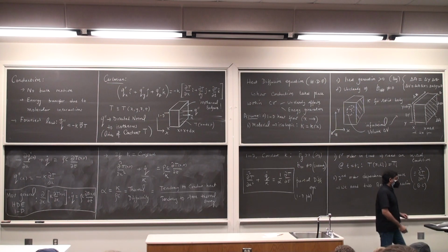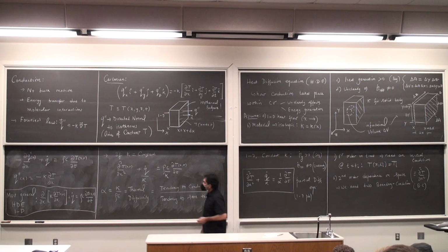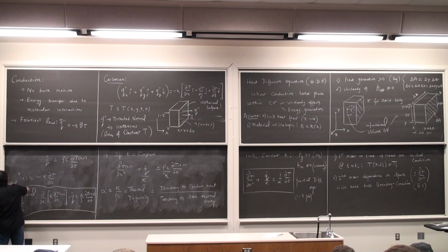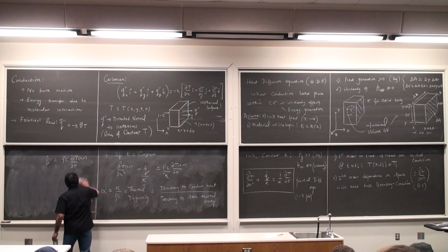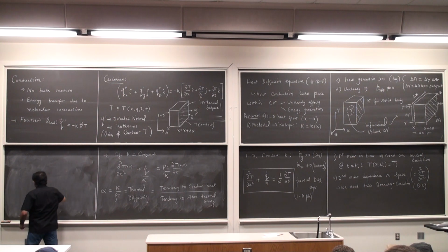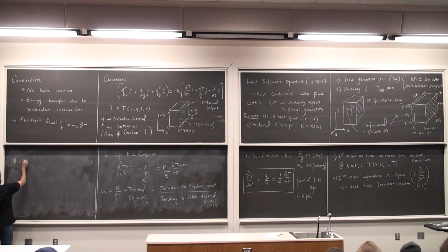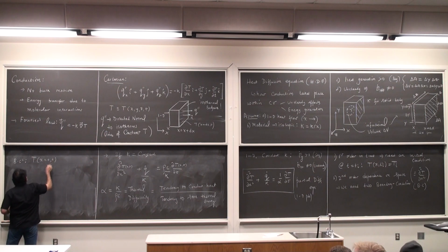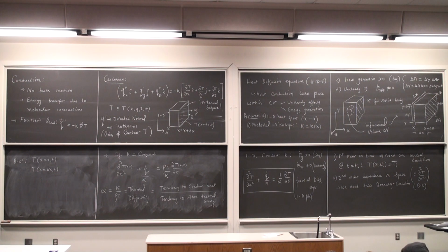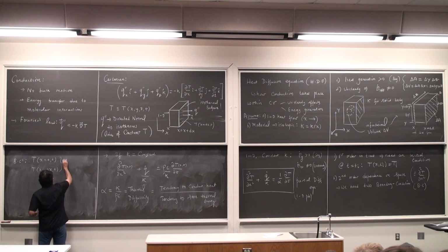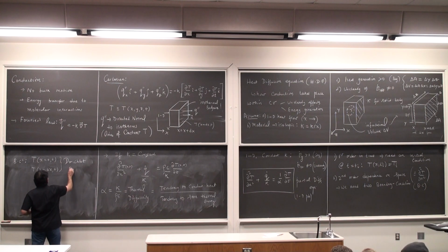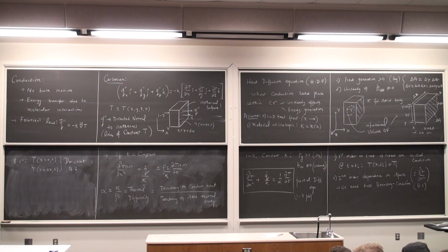These boundary conditions can be prescribed in 2 manners. One manner is where you prescribe the temperature on the 2 surfaces. So we are doing 1 dimension, right? So keep that in mind. So boundary conditions. I can prescribe temperature at x and temperature at x plus dx. T at some x is equal to 0, some x is equal to delta x. Okay. If I prescribe temperature on the boundaries, then this is called a Dirichlet boundary condition. I need 2 boundary conditions for 1D. Okay, once again we are restricting to 1D.